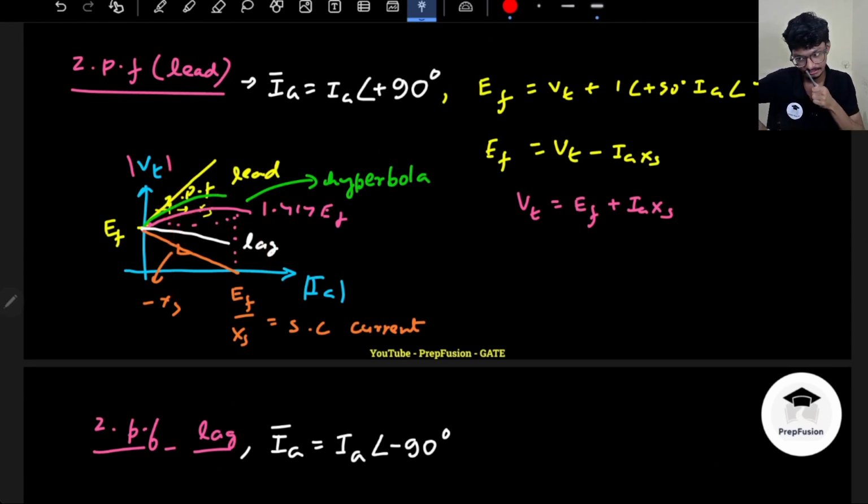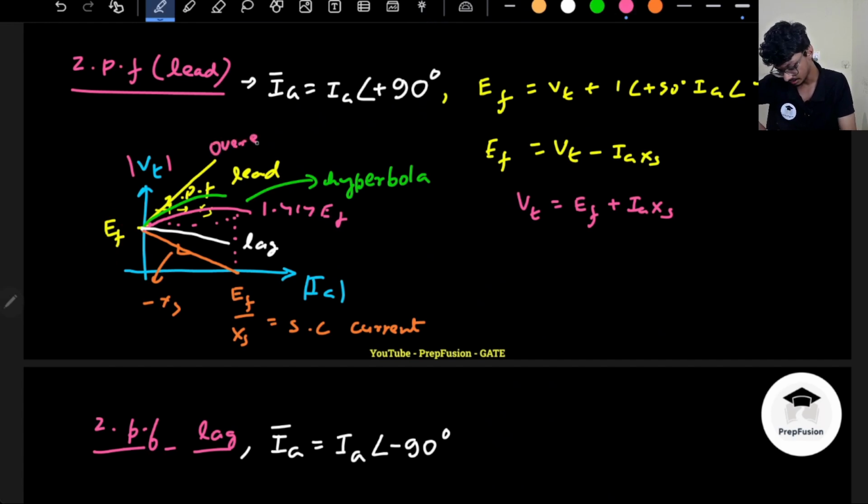Can you tell me why is the reason? The reason might just be that here it is overexcited. So for the same overexcitation, I do not need that additional armature flux, right? Whatever armature flux is there, that is aiding, so automatically the Ef is higher. Okay, so it is overexcited and underexcited. I hope you have understood this point. So here it is overexcited and underexcited.